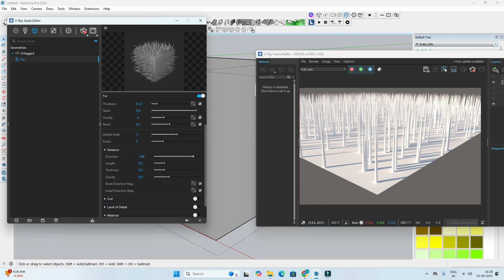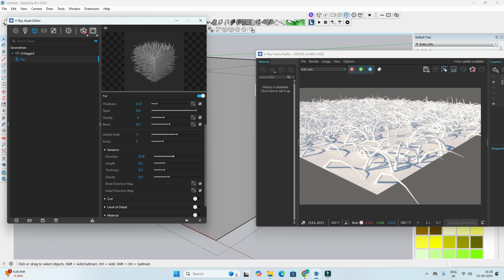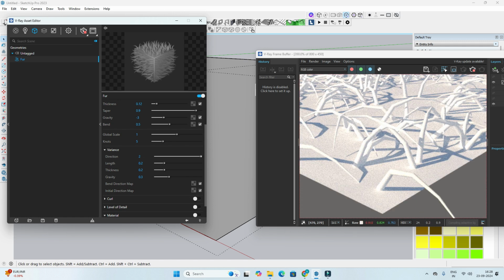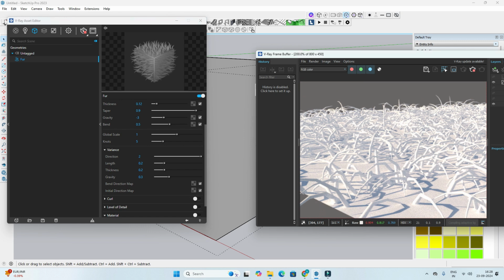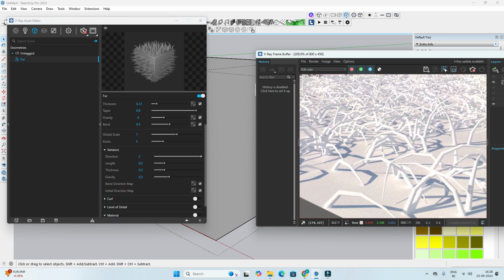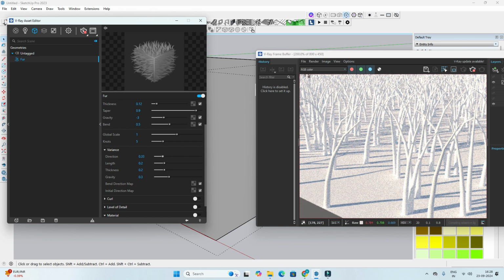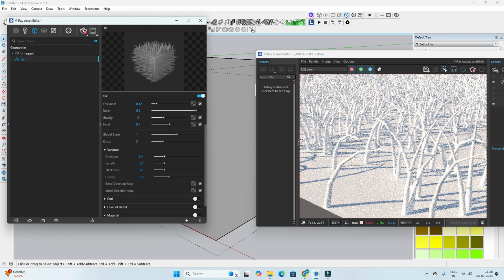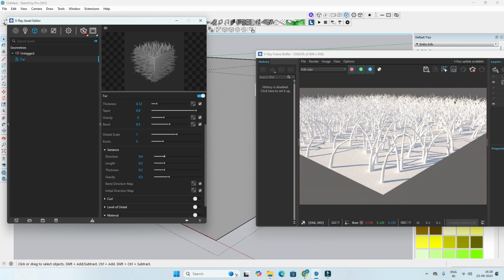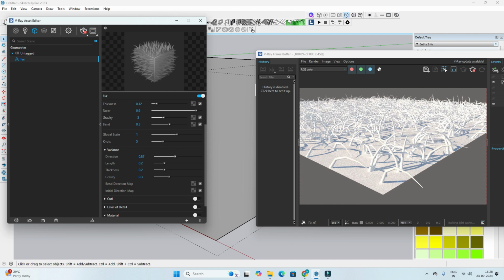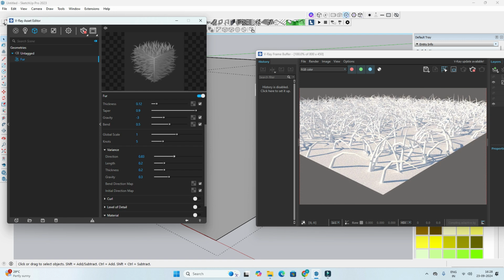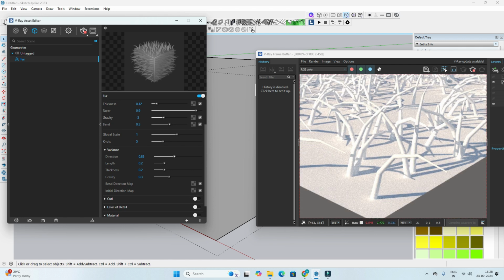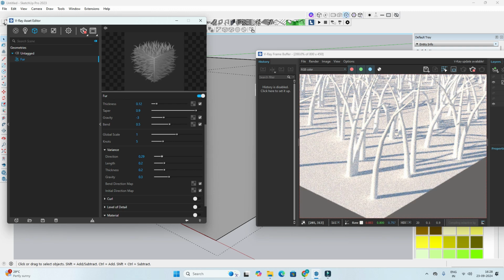Now if I keep on moving from 0 to 2, maximum is 2 and minimum is 0, and if you give this one to 2, everything is taking different directions, but it is not giving the original property. By default it is 0.2, maybe you can go with 0.3, 0.4, it depends on the situation. You can change these values. But don't give a 2 value or a 0 value. In between that, whatever value you want, but if you are crossing more than 0.8, everything is bending on the surface. Okay, now keep it maximum, maintain that at 0.2 to 0.4 value.